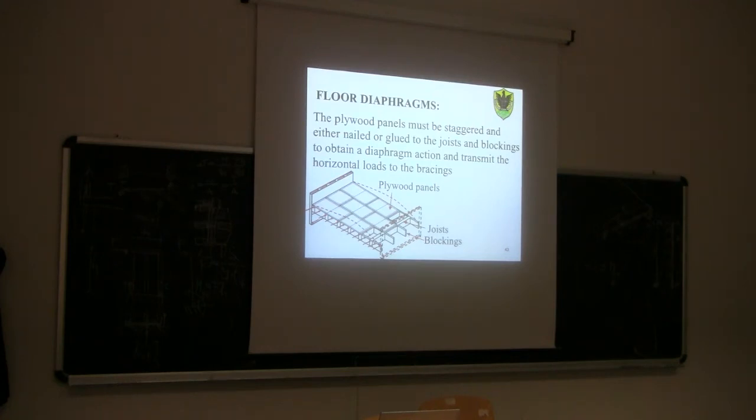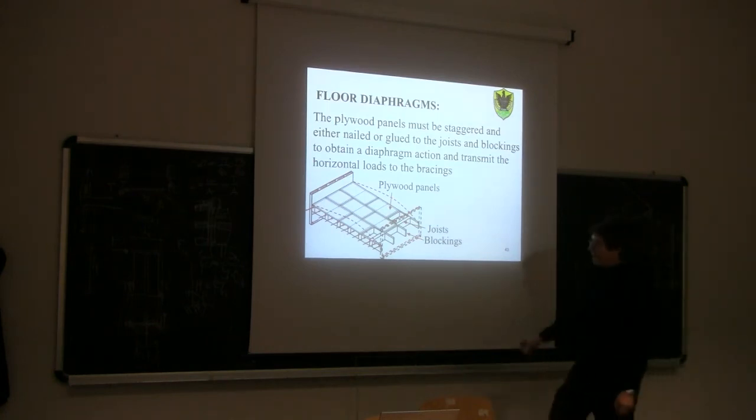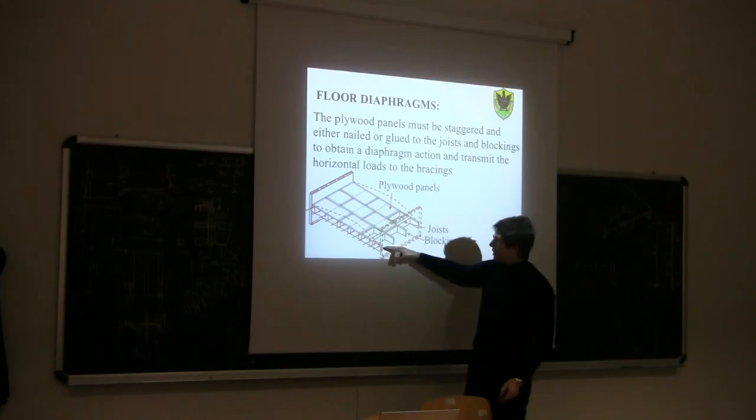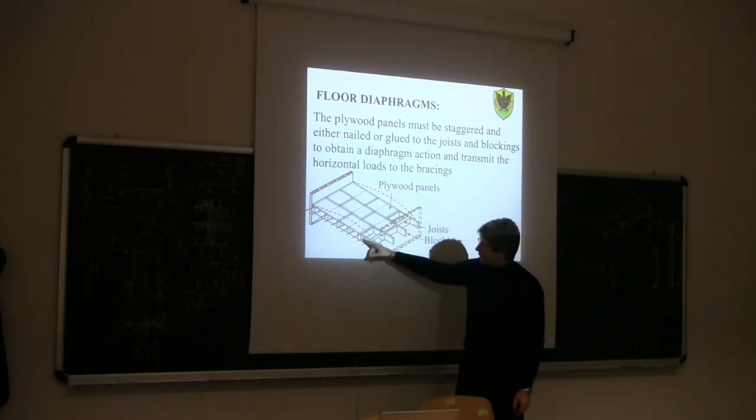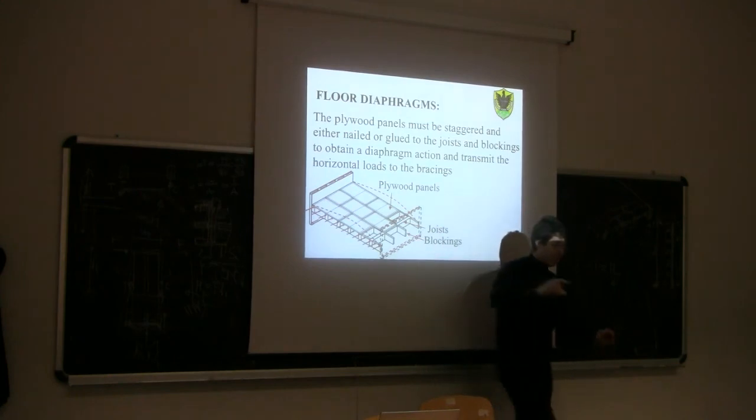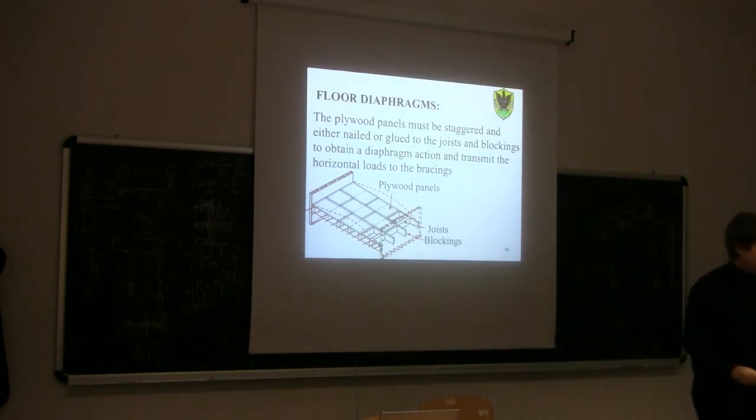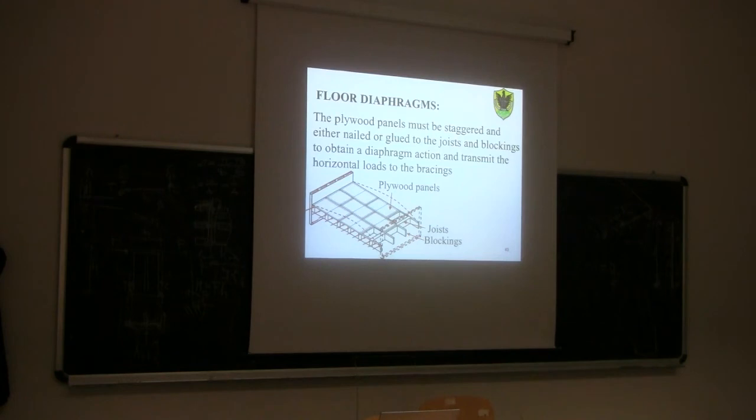Huh? I don't understand. Nail connection. Yeah, but nail connection between what? Is it easy to do a nail connection between this blocking and the joist and the plywood panels? Yes, but then you see, there is a problem, because you would need to transfer the whole tensile force into the plywood panel, which is not easy because it's very thin.